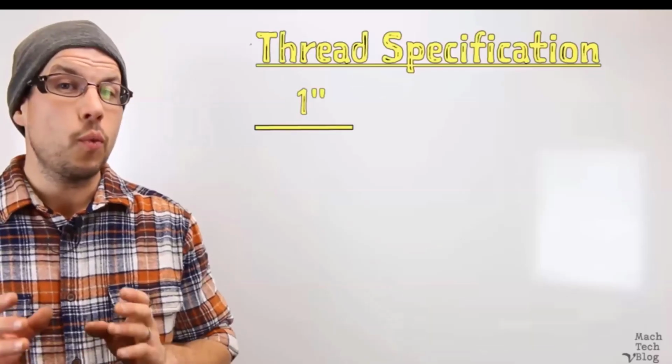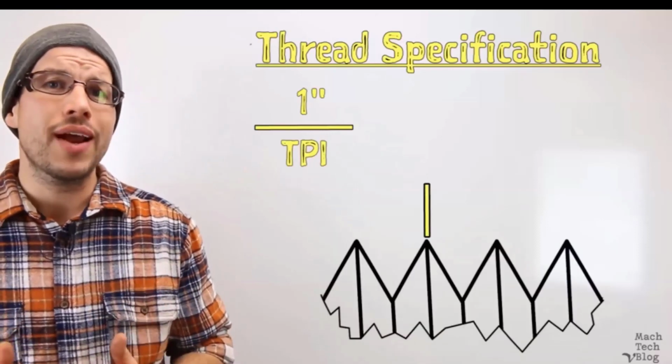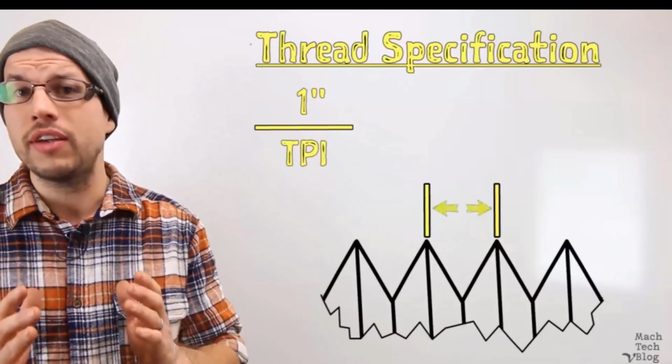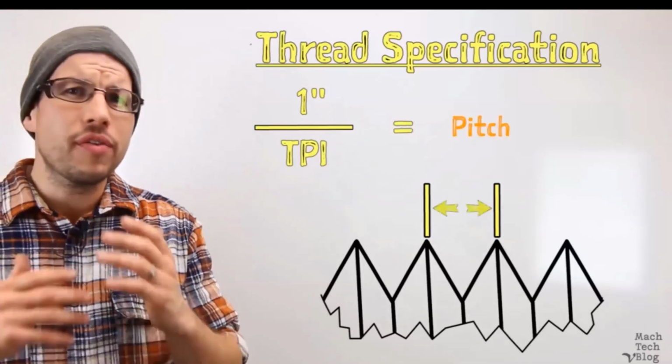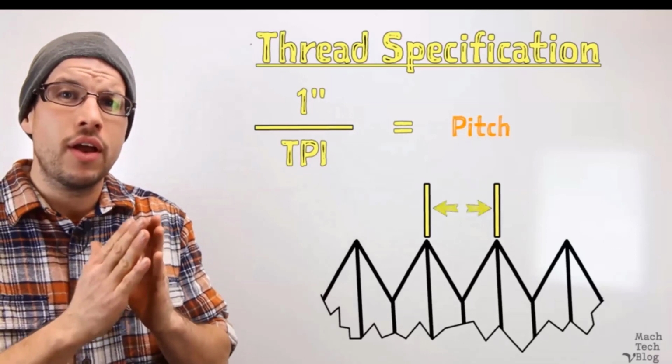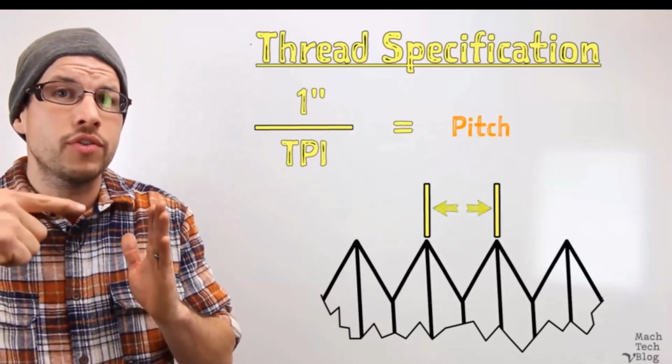If you divide 1 inch by the number of threads per inch, then you can figure out the distance between any 2 adjacent threads. This is called the thread's pitch. Another way of thinking about it is the distance along the length of the cylinder that it takes for the thread to make 1 full revolution.